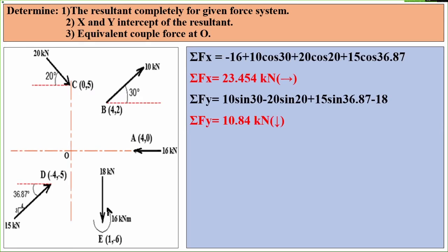Now all the steps are common: summation of Fx, summation of Fy. Only carefully resolve the given forces. If one of the signs is wrong here, the entire answer will be wrong.